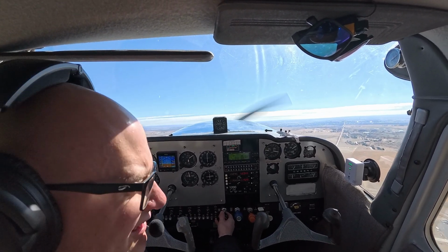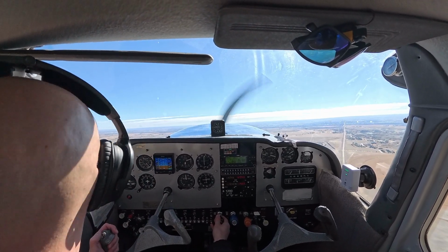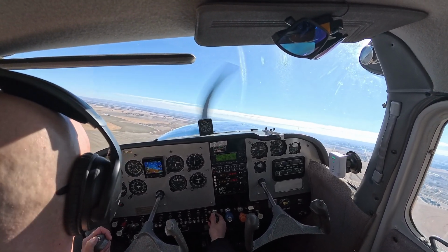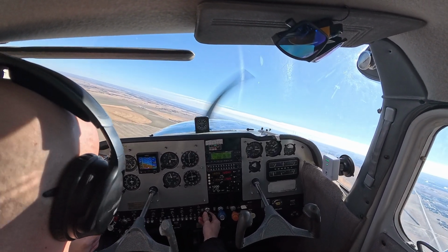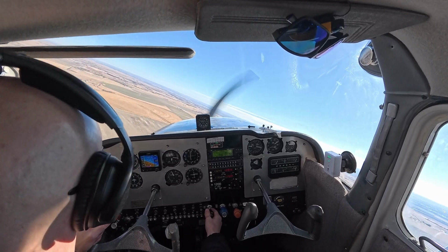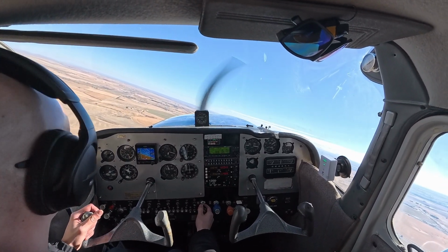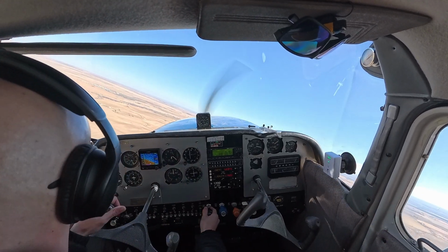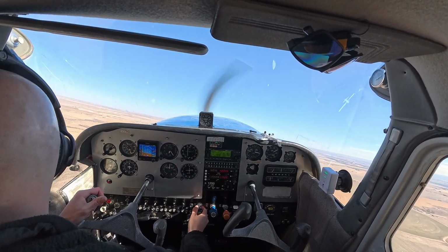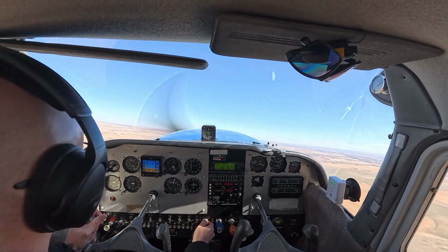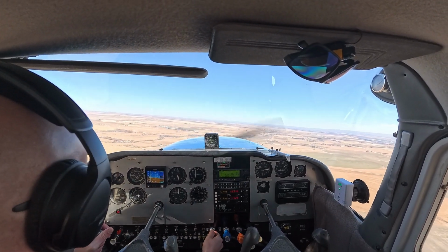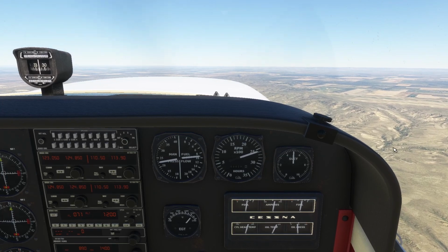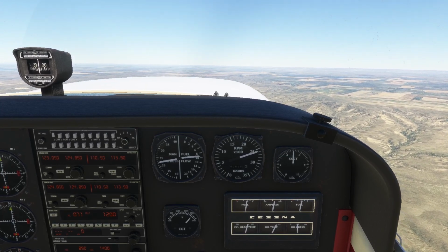Flying your airplane with high manifold pressure and low RPM is like riding your bike, pedaling really, really hard up a hill in a high gear. Now, there are certainly exceptions to that rule where you can, in fact, operate your aircraft with higher manifold pressure and a lower RPM. This will only be determined by the specifications laid out in the POH. If you are adjusting your power and you're ever unsure, as a good rule of thumb, always keep the RPMs higher than your manifold pressure.